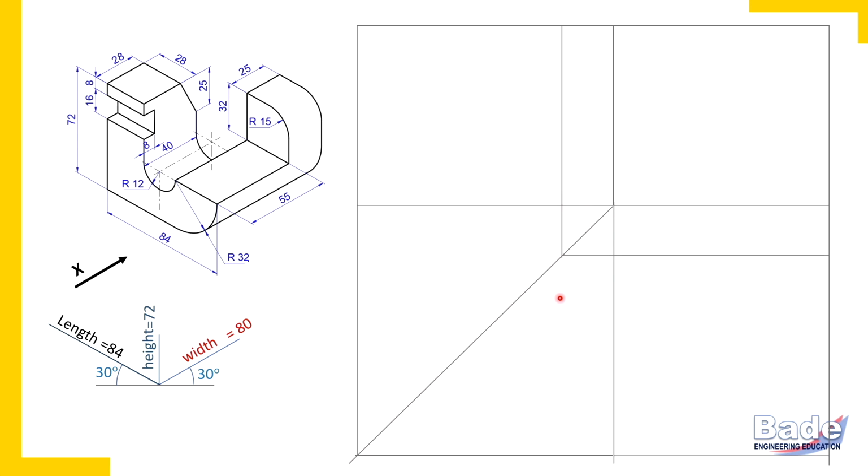Now we'll proceed. Here we'll focus on principal surfaces and principal edges. What exactly is a principal edge and what are principal surfaces? To know that, watch video number 2 on orthographic projections. Let's proceed. Now watch this surface. This surface has 2 principal edges which are perpendicular to each other. This edge, remember again, edges which are perpendicular to the reference axis are principal edges.